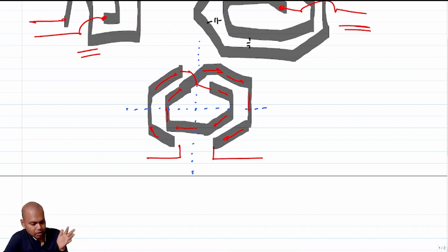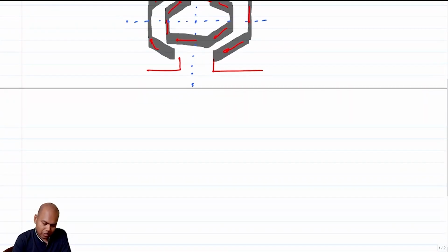So that is why whenever you have a process design kit, and you know that you are going to use inductors, it is better to characterize the type of inductors that give you decent performance, and then go ahead with it, right? So we saw some in the previous lecture. I talked about some models of the inductors, right? Those models are useful to characterize how good or bad an inductor is, but there are some other simplistic models that you can also use to give a not so accurate but a ballpark estimate of how good or bad an inductor is, right?